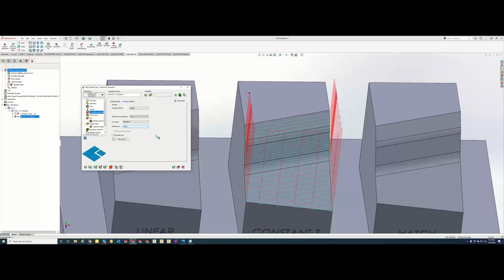So what this will do is, if we're trying to do multiple parts or multiple surfaces and there is a gap there, if I tell it to do it by lanes, it's going to skip over and try to do it all as one. Whereas if I would like to focus it on one specific part and then have it go over there, then we could switch it over to regions and it would keep it contained per region for you guys.